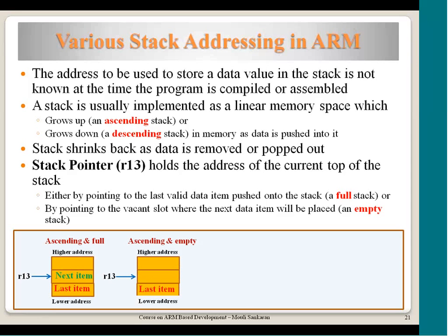This is the implementation where R13 is pointing to the empty location. So this is very specific to a processor. Now which is better? You can follow any convention because you can see that the number of operations done to push an item into the stack is the same, because either you increment the pointer after pushing this item, or you increment it before pushing the item.